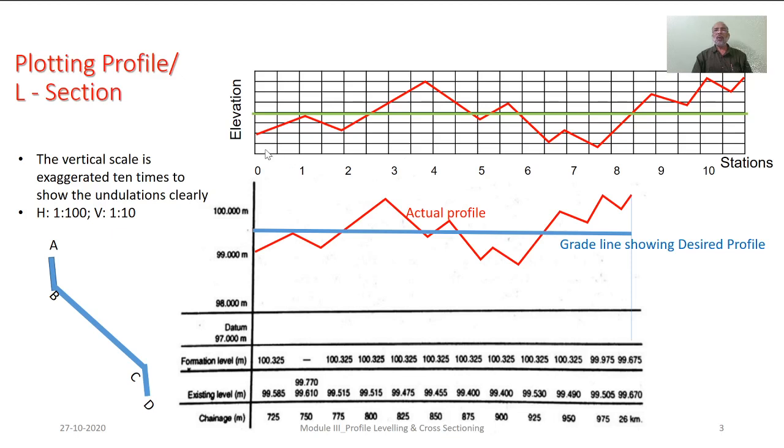It depends on the nature of terrain and the kind of result you wish to obtain. So, you can plot this line indicating the position of the stations. With respect to that, we can plot the various elevations that are worked out as ordinates. Accordingly, we will be able to determine the exact profile of the land lying in between the stations under consideration.